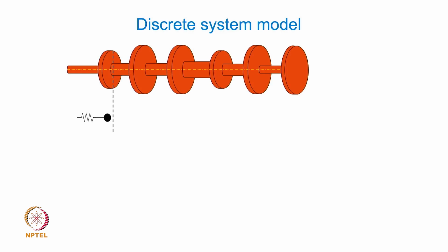So if this segment represents this inertia and this spring, the spring is essentially representing the torsional stiffness of the shaft, that is going to resist the twist in the shaft. And obviously when it undergoes a torsional vibration, this represents its mass moment of inertia about the axis of the shaft, right. So that is basically how the inertia and stiffness elements define together one particular segment.